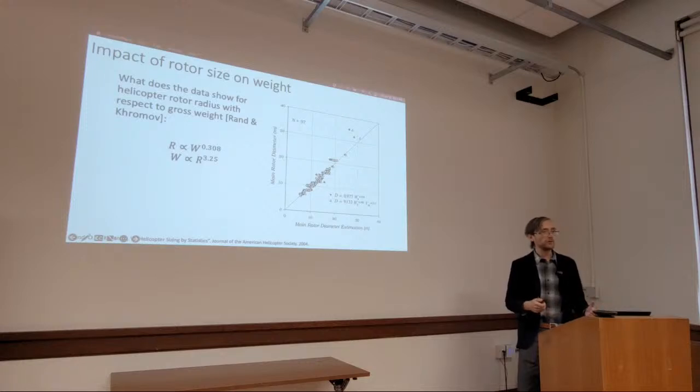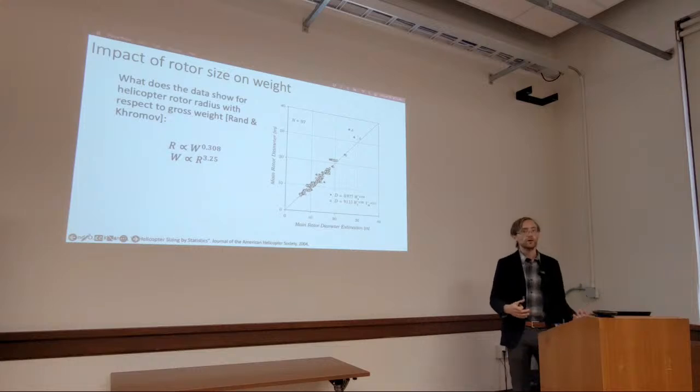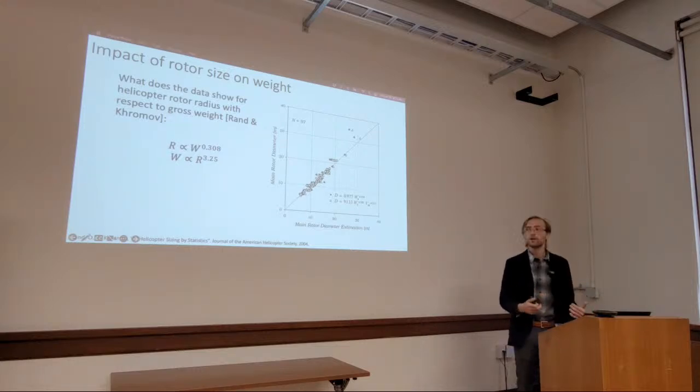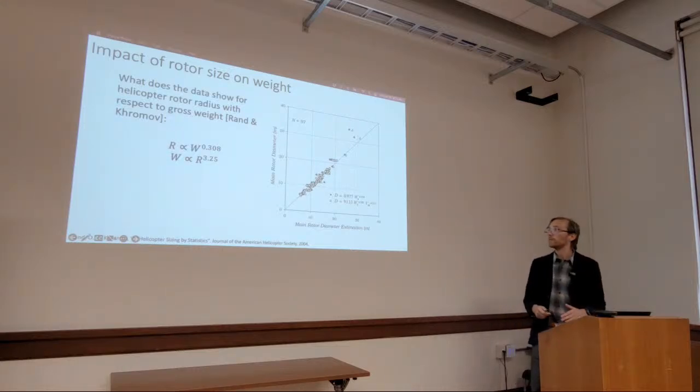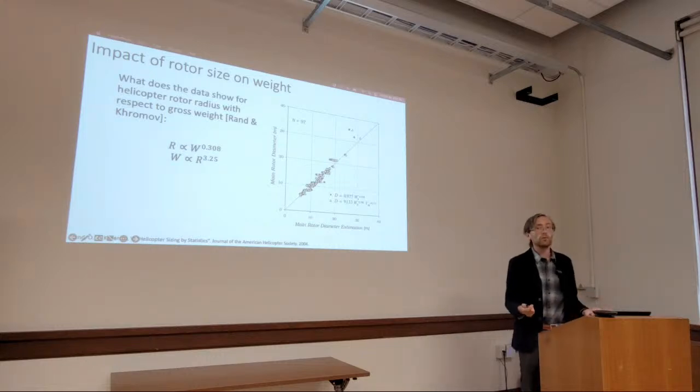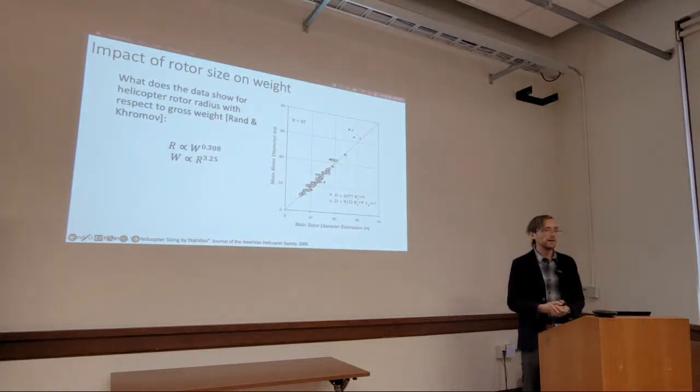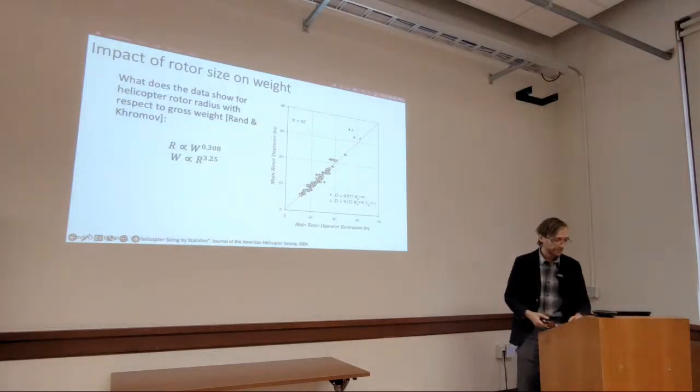Potentially because the example of the cantilever beam is not the most efficient structure to sustain its own weight. So if we look at a more efficient structure, it would have something less than r to the power of 5. But in any case, there is some dependency that is shown in data on existing helicopters, that therefore must be guided by some inherent physics principles regarding the design of helicopters.